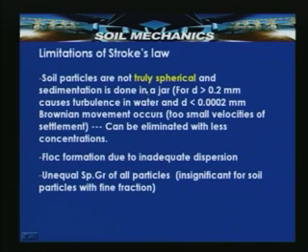So, we have seen the Stokes law application for determining the fine grained soil fraction, and we said that the first and foremost assumption is that the platelet particles or fine grained soil particles are idealized as small spheres. As we know, soil particles are not truly spherical, they are far from spherical. Also, sedimentation is assumed to occur in an infinitely extended medium, but we are doing it in a jar of limited dimensions.